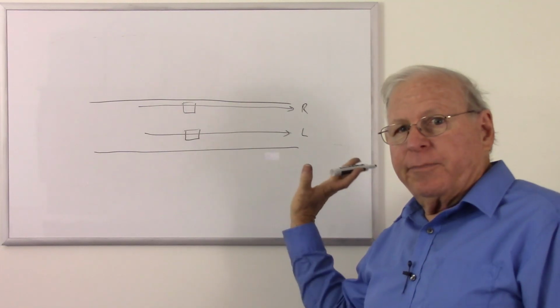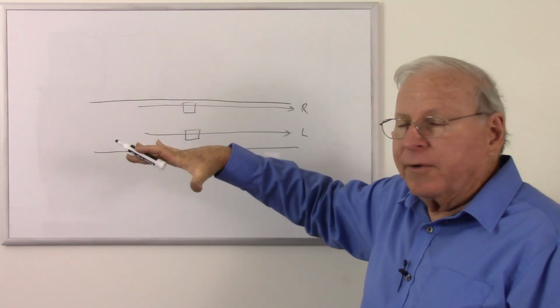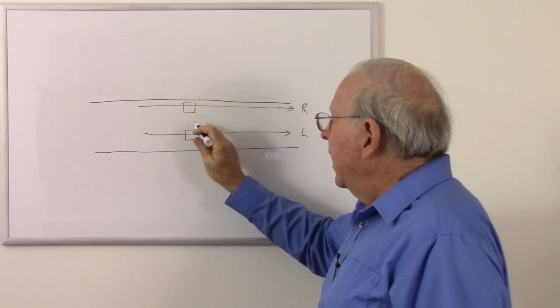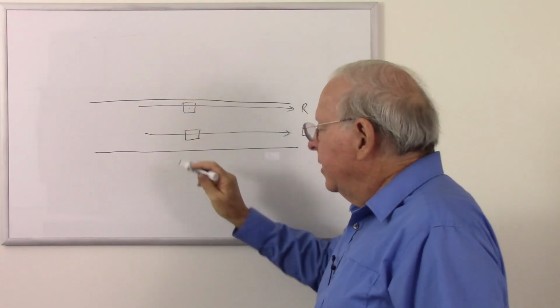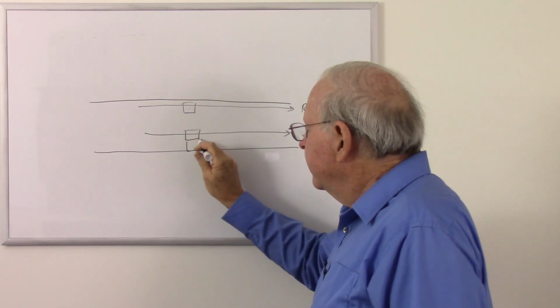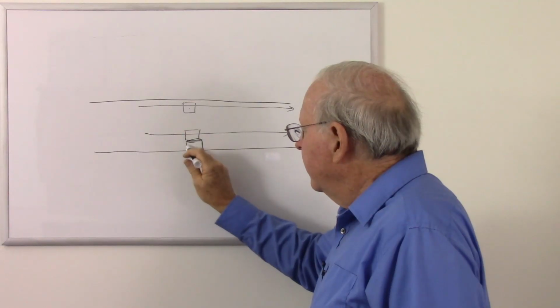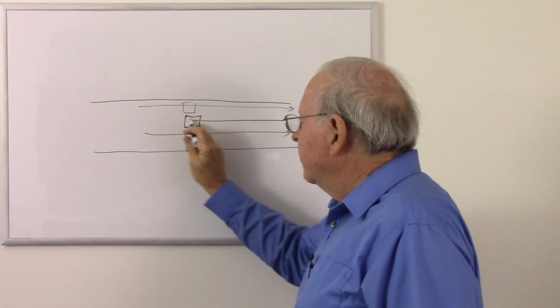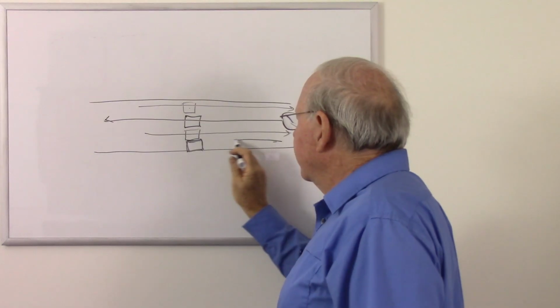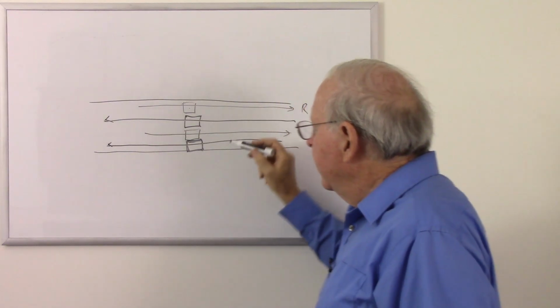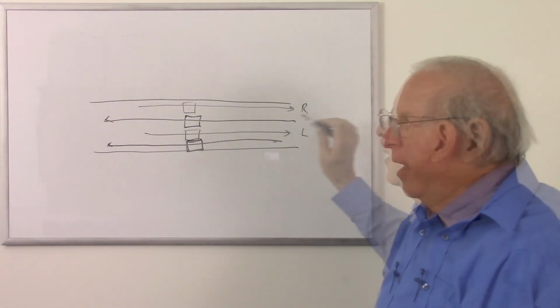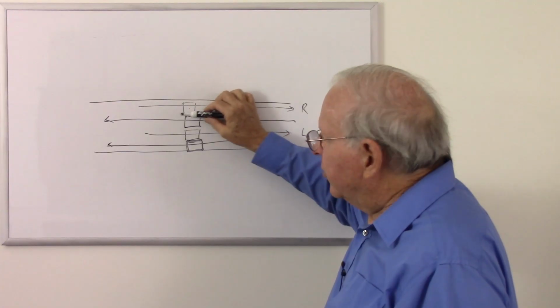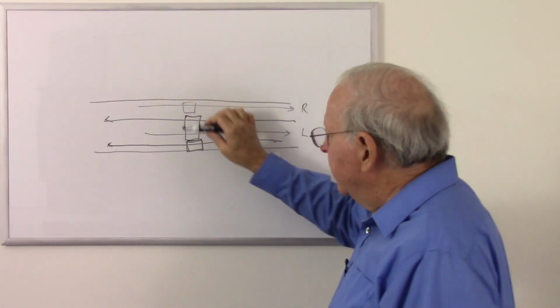Then what happens when you flip over the tape and run it the opposite direction? Well, now this head is here. I'll just draw it darker. And this head is now here. So recording the opposite direction, it would record that way. I don't know why they staggered the tracks like this. You know, there would be a little bit of a space that's not recorded. That's called the guard band between the tracks.